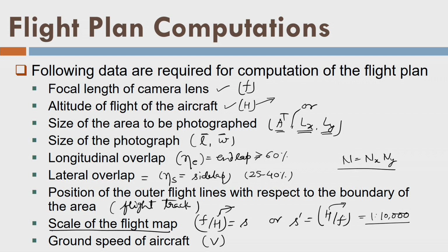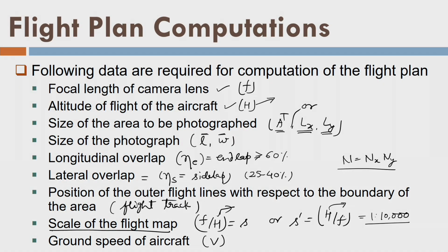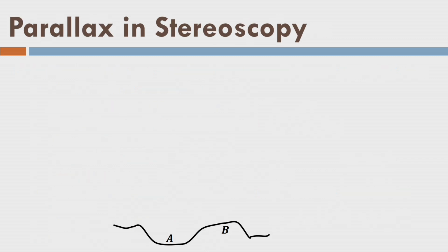So, what could be the possible cost in the field if I acquire so many photographs? Beforehand I know what will be the projected cost or what is the likely cost. So, should I go for this kind of mission? Because what is the accuracy I am going to get by this data acquisition in my real map? Does it really worth to go for this exercise or the data acquisition or to create such map by aerial photography? So, that kind of judicious decision I take by flight planning only, and that is the importance of flight planning, right.